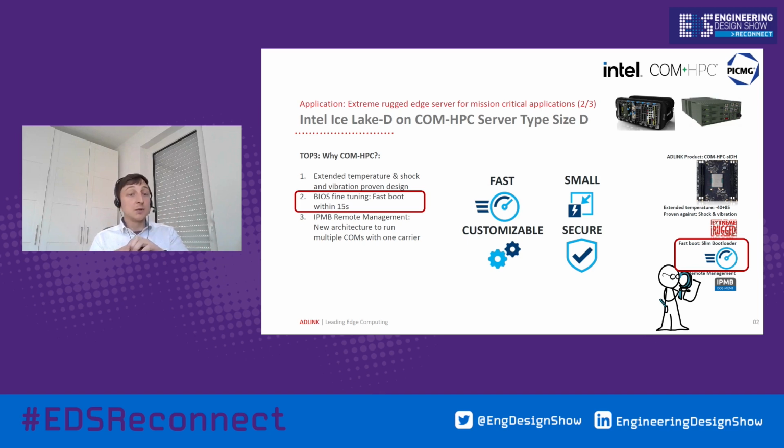And then it allows fully redundant images for resilient solutions. It is designed with modularity in mind, allowing for easy implementation of further changes and differentiating features. And last but not least, it has to be secure. It supports verified boot, and secure firmware updates are standard, and so on. Secure boot options when paired with Intel Platform Protection Technology with Boot Guard is a key differentiator, just to name one of them.